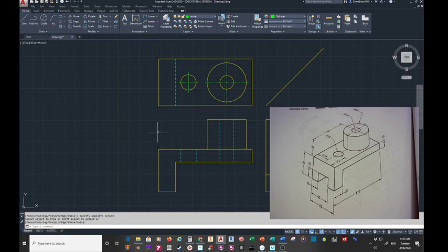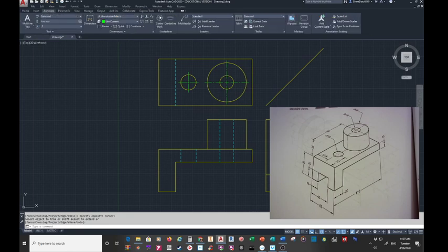Alright, this view is almost done. This view is really close. And so now, first of all, I'm on the centerline layer again. So I'm already on there. So I'm going to go to annotate. I'm going to pick center line this time. Now, the center marks, I get people to use center marks, but then they don't come in here and use the center line command. And this thing is awesome because you just pick these 2 lines and boom, there it is. It's great.